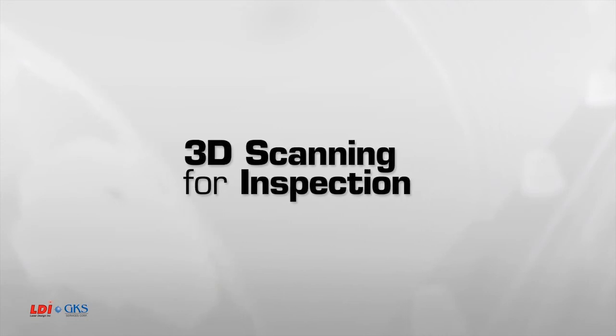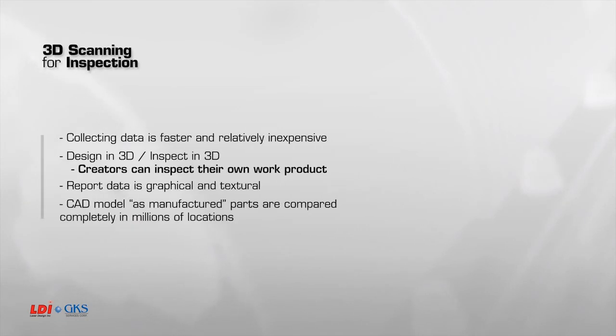3D scanning for inspection. Collecting data is fast and relatively inexpensive. You design in 3D, so why not inspect in 3D and allow the creators to inspect their own work product? As you'll see, work product and reporting is graphical and textual. The CAD model is inspected as well as the as-manufactured part, which is scanned, compared, and measured completely in millions of locations simultaneously.